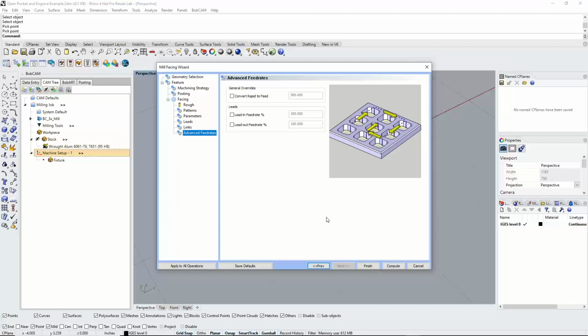Now, this is common. The reason you'd use this is usually because a machine is dogleg rapiding. So what that means is instead of doing a straight line rapid, your X or Y, depending on where you're going, one of them kind of moves faster than the other, because when we go into a G00 move, all rapid moves move to their fastest travel, and it becomes non-interpolated motion. And so essentially the G00 is what's causing this.